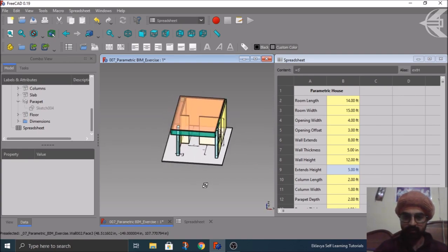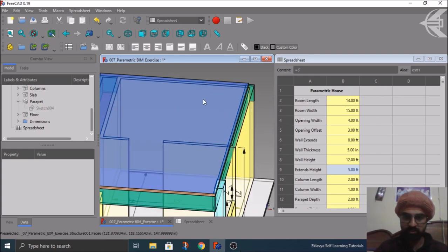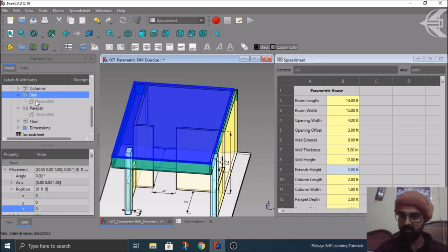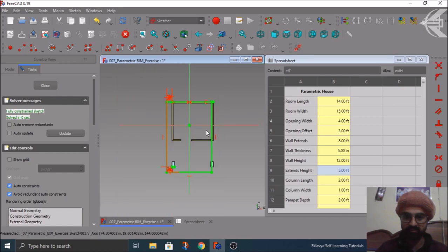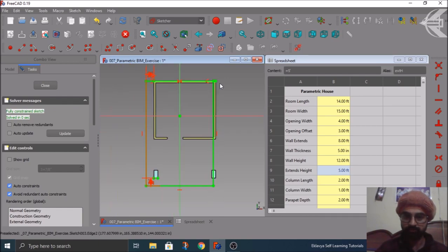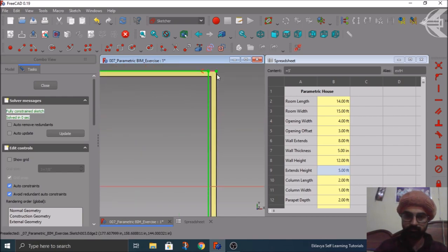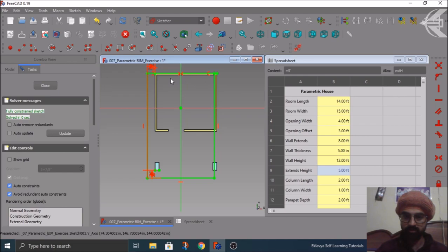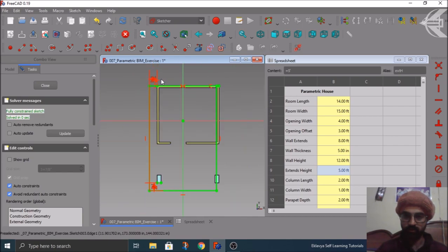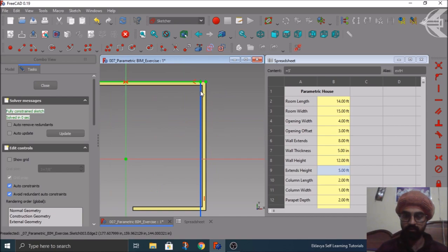Fine. Then this slab is actually creating a problem for your overall thing here. So this slab is not getting rightly constrained, as you can see. It is constrained. So this was supposed to be at a certain offset, which you have given here, 2 feet by 2 feet.